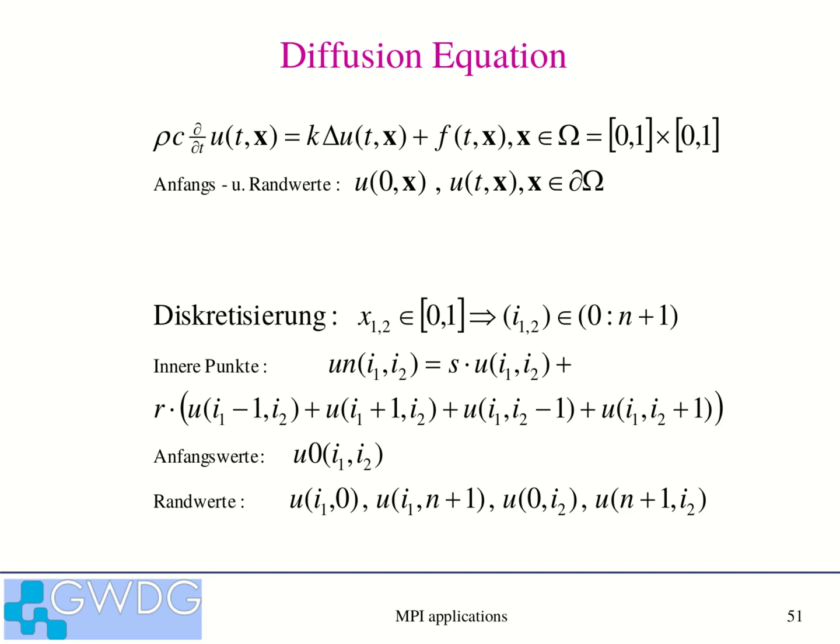Well, for us, using computers, we cannot solve continuous equations. We have to discretize this, and discretization means that you put points on your domain, grid points, and then you consider the value of the property only at the grid points.